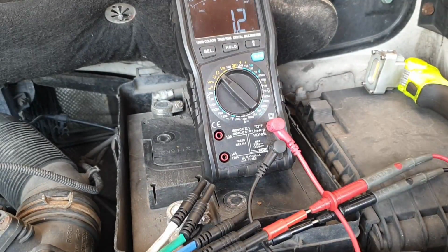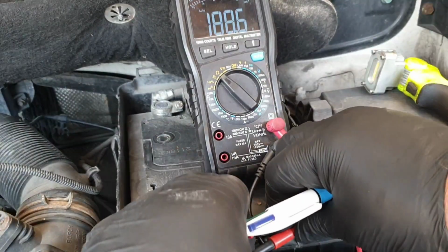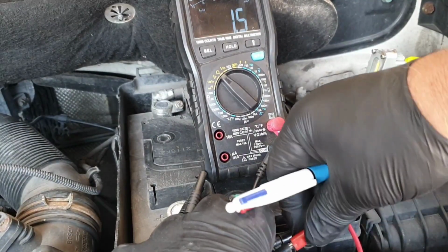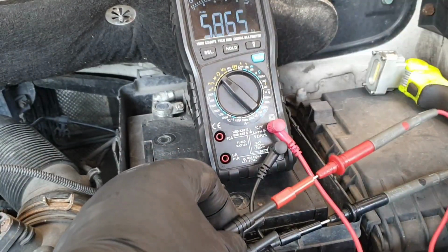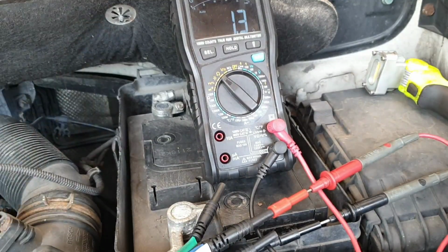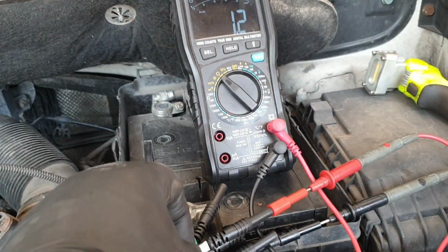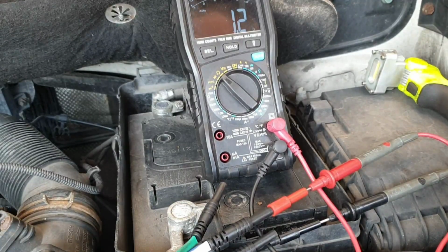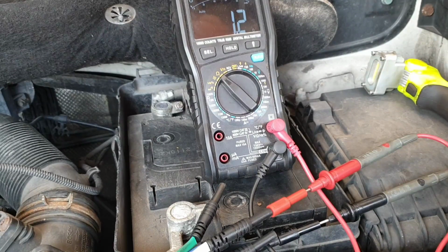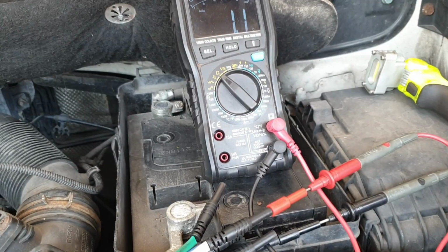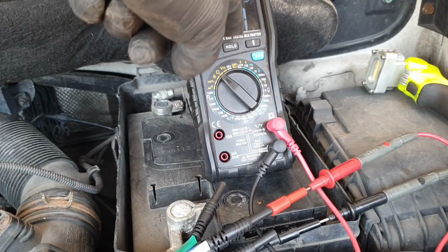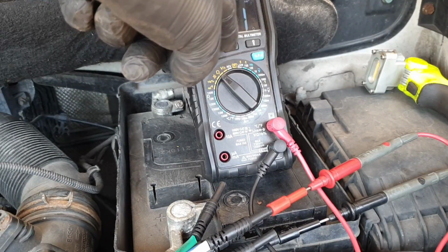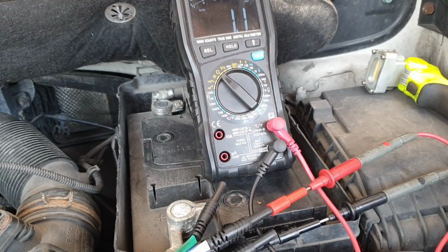So moving to injector number 4, which is the white lead, and this is also 1.3, as you can see, injector number 4. So 1.2. Okay, now this is the value that we got. Now this injector number 4 resistance value drops to 1.1. So this is the value we got from the 4 injectors.